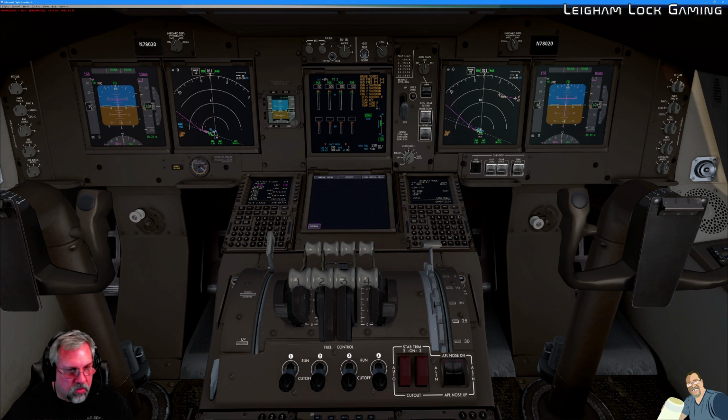Parking brake set. Now we could do that, but I want to point out, notice over here that our brake pressure is just about 0, so we don't have much hydraulic pressure in the brake system, and you can see that we have a warning light here for brake source. So although I could turn on the parking brake now, which is right here, there's really not a lot of pressure to hold the aircraft in place, so I wouldn't certainly rely on it. And that'll change here once we activate the hydraulic system number 4 electrically. But we'll go ahead and we'll set the parking brake right now.